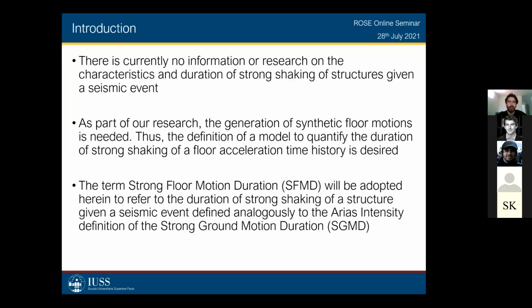So, introduction. There is currently no information or research on the characteristics and duration of strong shaking of structures given a seismic event. What do I mean by this? There's a lack of information regarding the amount of time a structure actually shakes during and after an earthquake. We know a lot about the response, the stiffness properties and the damping and a lot of things, but there is no research about the duration that the structure actually shakes, because it's not necessarily the same as the duration of the ground motion, as you can imagine.